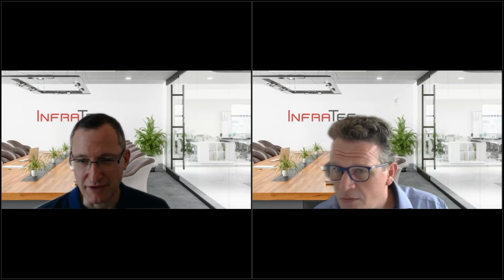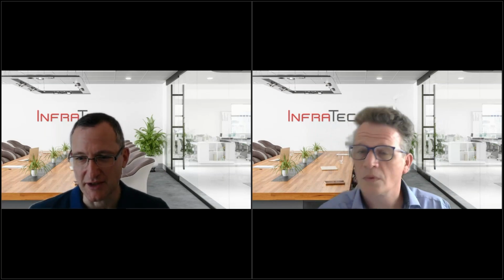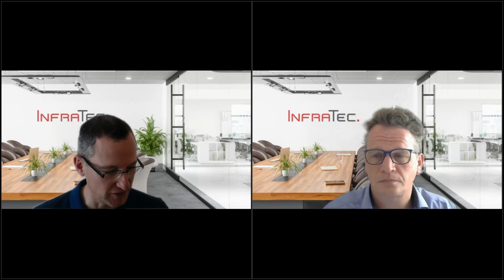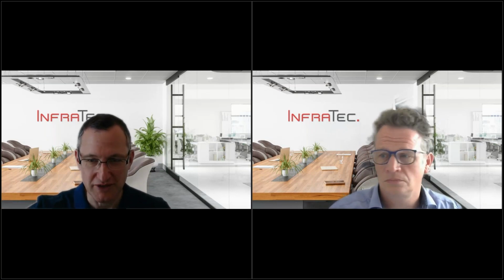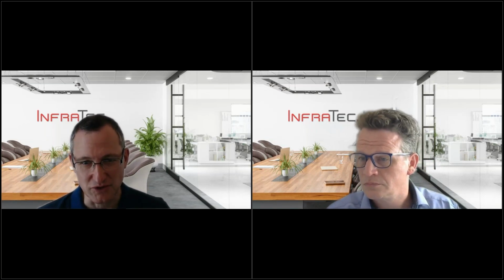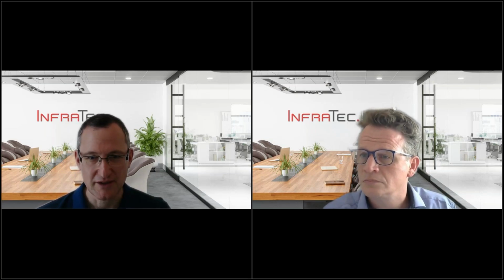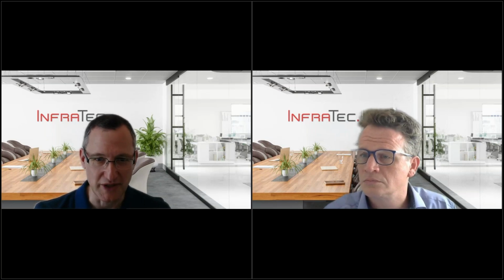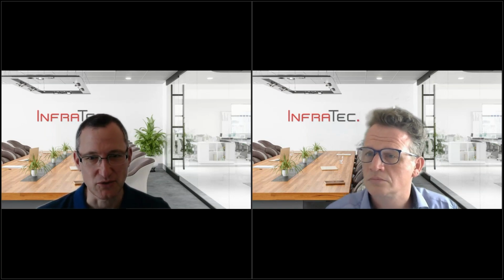I found one more. How do you keep the objectives clean in industrial environments? So I think one thing that was mentioned is air flushing. Of course, you can use a protection window in front to protect the lens, but then you still have to make sure that this doesn't get dusty. So it's air flushing. In some applications, as you have maybe seen in the presentation, you can also make a lid and close it, so that you protect the camera when it's not used. So there are multiple ways to deal with dust.